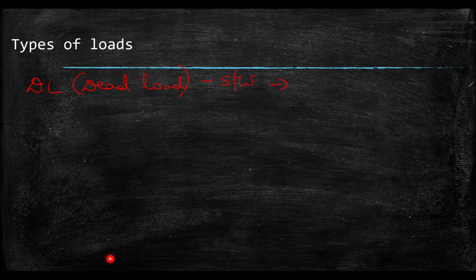Normally how we get it is, we take the length, breadth and height of the structure multiplied by the density of concrete in the case of concrete structures, or the density of steel in the case of steel structures. If you multiply that, you will have meter cube, and the unit of density will be kilonewton per meter cube. So you will get kilonewton, that is the weight of the structure, and the structure should be capable of resisting that load. That's why failure under dead load is the main cause of structures which fail during construction itself. Next we have the live load.